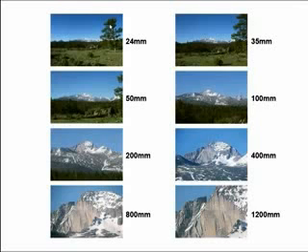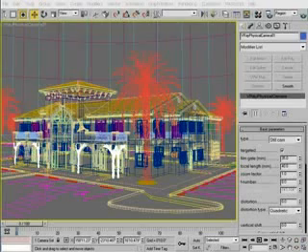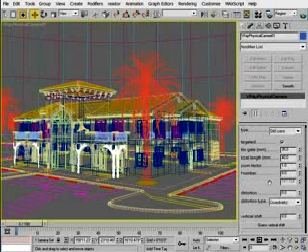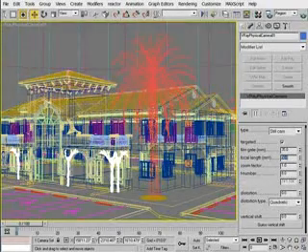At the wide angle extreme, objects are distorted from the way they're seen by the human eye, and at the telephoto extreme, objects are not so much distorted as they are blurred, or at least not in the range where objects are in focus. Well, the human eye sees objects similar to the way objects are seen with a 50 millimeter lens, and by this I mean what you would see with one eye open, not both. So a 50 millimeter lens is considered normal and is what you would get most often when you purchase a camera. So within the VRay physical camera settings, place your focal length at 50 millimeters if you want the quote-unquote normal view with your camera.